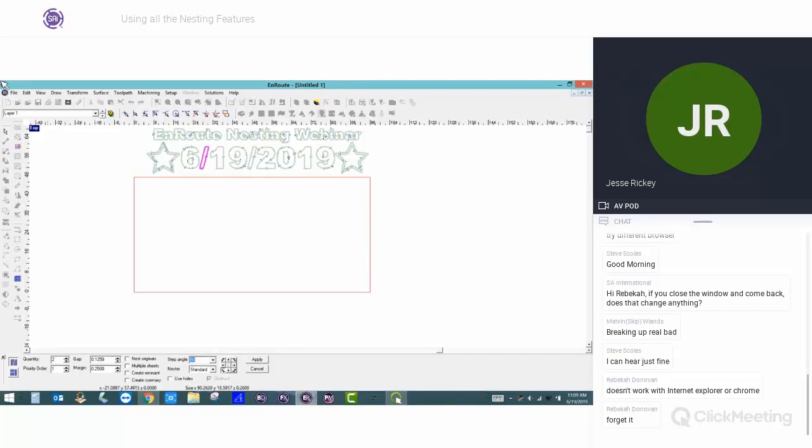Earlier, like I said, I have a habit of moving my parts outside of my sheet. That is because generally I do not use the standard, I use the new one. With standard and legacy, those are two different versions that have very similar algorithms, but they nest parts in different ways. The reason that I pick the new nester is there's one extra option that I have, which is obstruction, which we're going to cover.